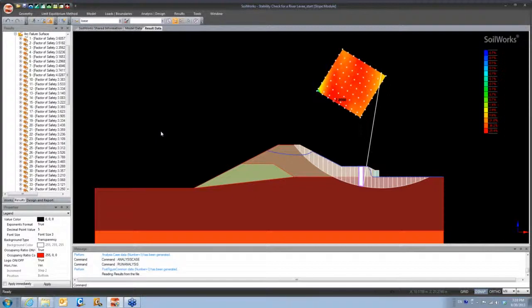There's just one more question I have for you. It's not along the line of the hyperbolic model, but let us say you're doing the construction of an open dam. You'll be constructing it in layers. Here you presented a full embankment, a completed levee, and you're probably just running a seepage analysis on the levee itself. But during construction, there is a great possibility that the embankment can fail.